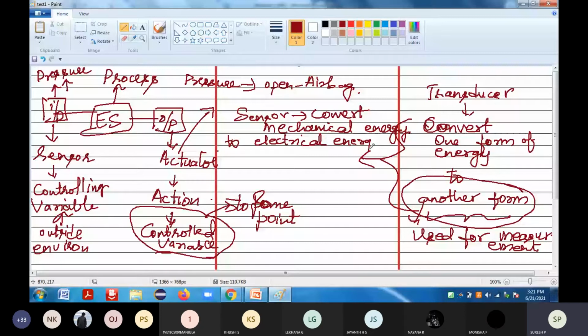They are interfaced using a translating system like ADC or optocouplers. Instead of being connected directly, the sensor will be connected to the ADC. In between the sensor and the input port there will be an analog to digital converter, which will convert the signal, and after that it will connect to the input port here. So they are not connected directly to the input port; they are interfaced using a translation system like ADC or optocoupler.